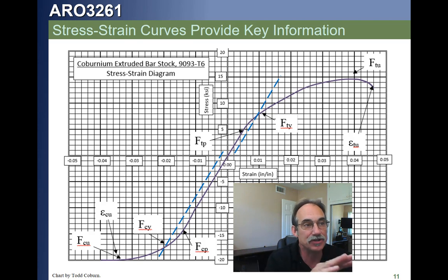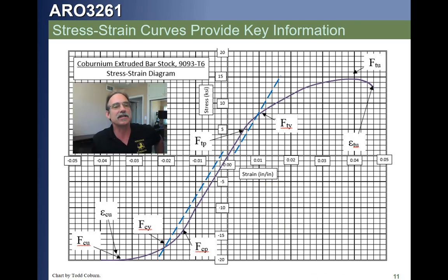So if we see a stress-strain curve that's full range, meaning it shows the tension and compression behavior, we will use the entire curve to evaluate our material. If we see only a first quadrant stress-strain curve, we will just guess that that material is symmetric enough and pretend that the compression behavior is identical to the tension behavior. Does that make sense? So let's look at some points.